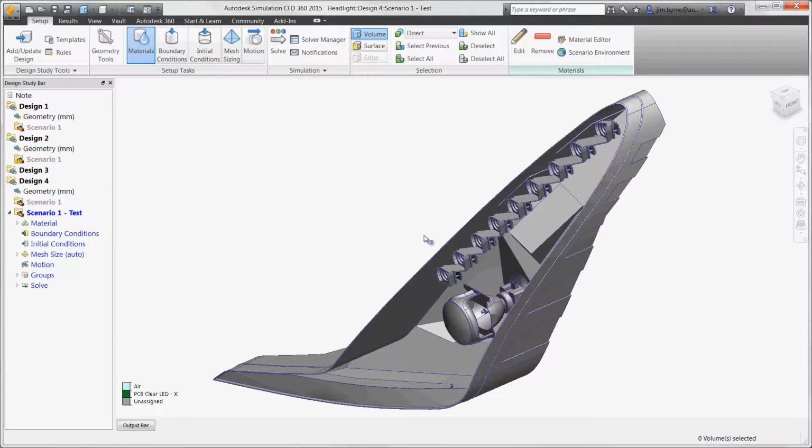We're going to analyze 3 different sets of lights in this fixture. There is the main HID xenon light, as well as the LED lighting above and below. Combination lights such as these create new challenges for OEMs and exterior automotive lighting suppliers. Our goal in this design is to preserve the clarity, brilliance, and life of the LEDs. In order to do this, we have to keep the LEDs within operating temperature and also minimize the temperature difference between each of them to avoid color shifting.